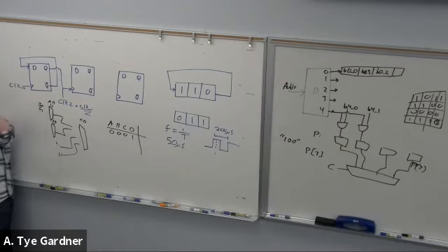Constant m unsigned, right? Make m an unsigned constant, and then have the thing that it's comparing against be a standard logic vector. And then that would be a code error, right? Because I can't compare a standard logic vector to an unsigned, even if they're the same length. I would have to do a conversion. I won't ask you, I don't think, to write out a conversion because they're annoying anyways, and I hate them.